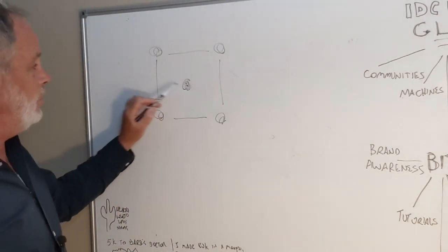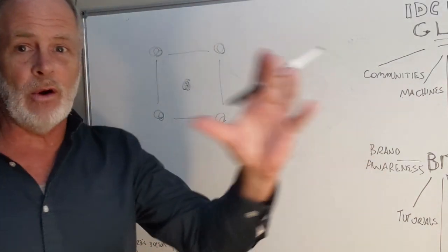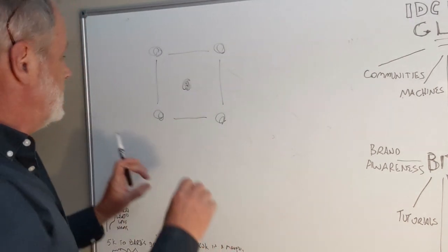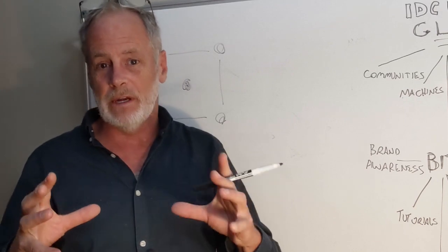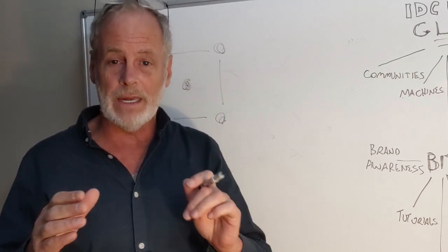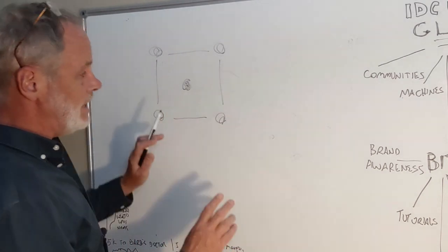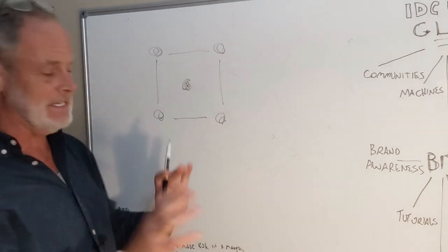So if you select the middle dot, it doesn't matter where on your design that rectangle is placed. What this is telling it is how the rectangle is going to form, or where it is going to be built from. So we have the center dot selected. That means this one, this one, this one, and this one are not selected.